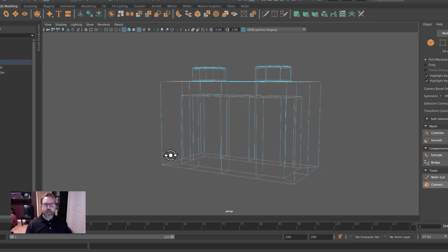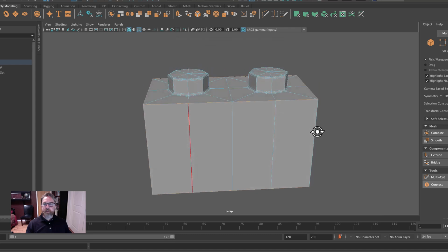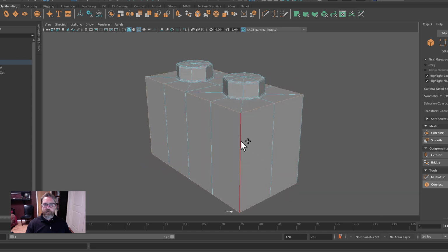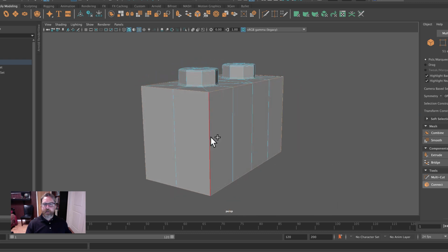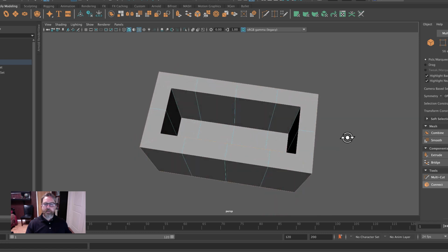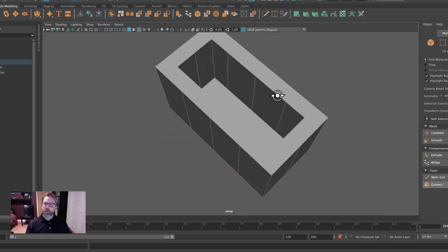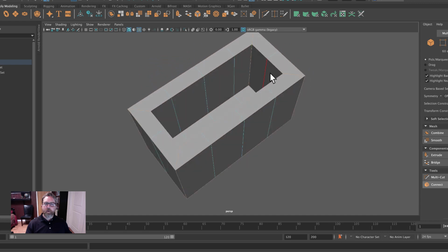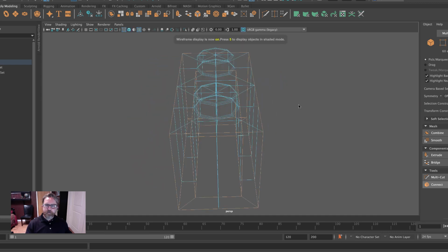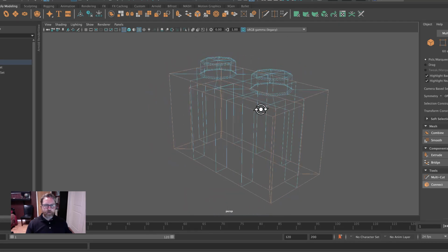Now we'll come and select the corners. So we've got these 4 corners on the outside. Shift click. I'm not double clicking because that would select this edge up here, and we don't want to bevel that. So manually selecting, shift click, not a double click this time. Shift click, shift click, shift click, shift click, the 4 diagonals, and then the 4 interior corners. 1, 2, I'm holding the shift key, 3, and 4. And so that is the complete selection of edges. And if you missed one or had one you didn't need, you could simply undo.